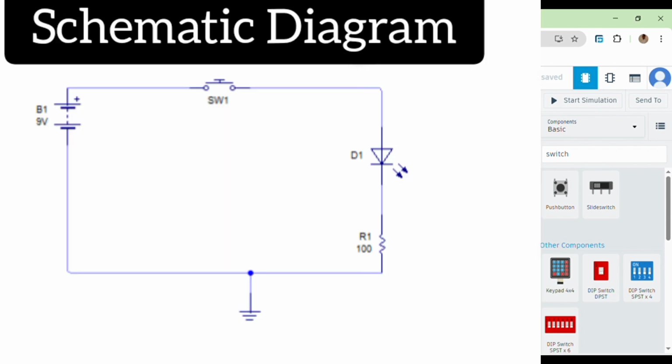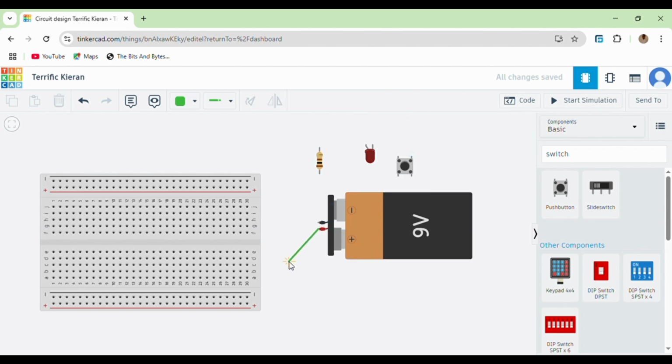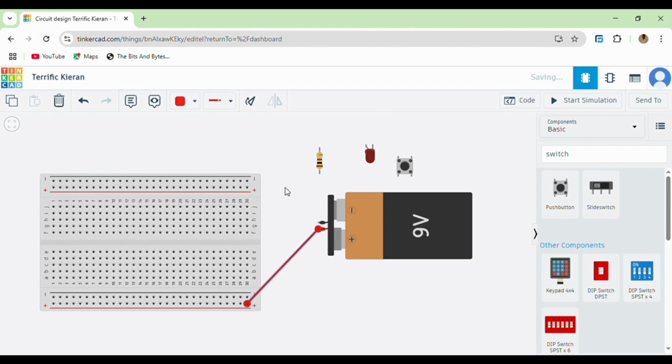the circuit development. So the battery has two polarities, positive and negative. Connect the positive of the battery to the positive side that is marked on the breadboard. I'll change the coloring to red to show that this is positive, and then the negative side of the battery is connected to the negative side marked negative on the breadboard, and then I'll color this to be black. Perfect.